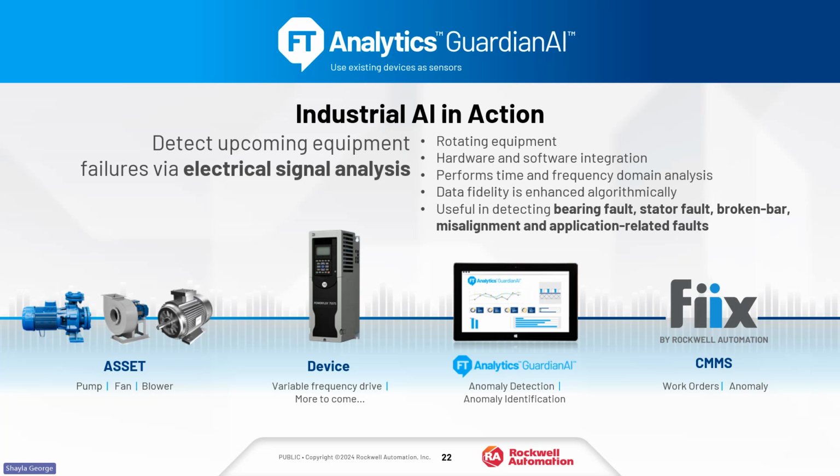So the drive is connected to the asset, and then Guardian AI is a piece of software that sits on an edge device, whether that is a Rockwell 6300 industrial PC edge device, or a compatible third-party edge device, as well as a virtual image. So the software, it's a container software that's on that device. And you connect the drive to Guardian AI software using the IP address of the drive, and then you start doing the training and the modeling of it.